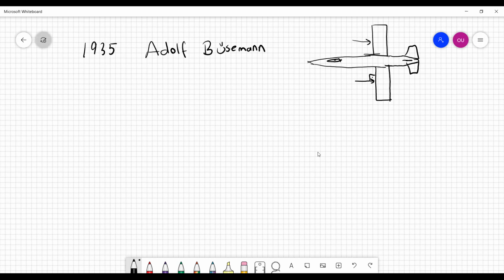So by sweeping, the thing is, when you start to fly, let's say your M infinity, you have a certain airfoil section and some M infinity approaching. If it's not swept, with zero sweep, as it was said in the video and as we discussed yesterday, we start to see supersonic regions, and as M infinity increases, these supersonic regions become bigger and bigger.